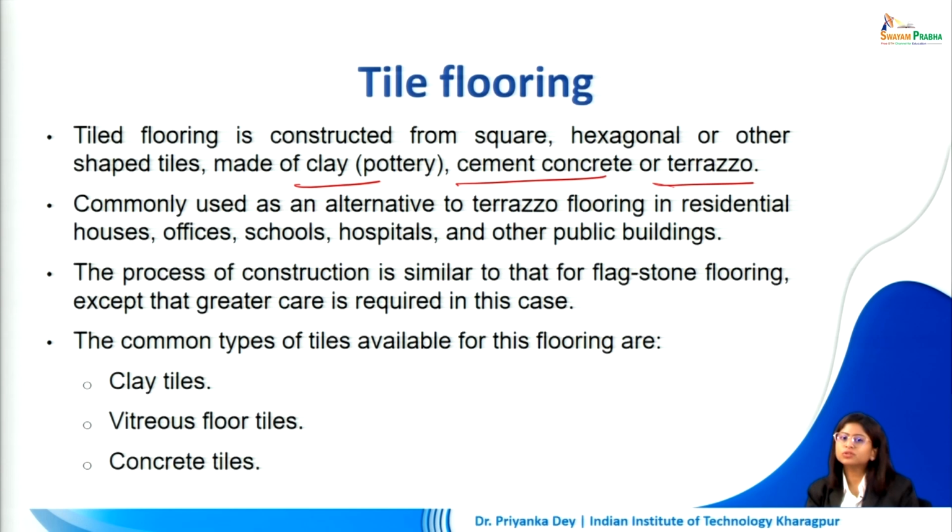Now, the process of construction is very similar to the flagged stone flooring that we had just studied, except that greater care is required in this case, especially if you are dealing with ceramic tiles or vitrified tiles, which can easily be damaged. During site construction, it is possible to damage the tiles if excessive force is used while fixing, or if not enough gap is provided between adjacent tiles. In that case there might be damage either immediately or through seasonal expansion and contraction of the building